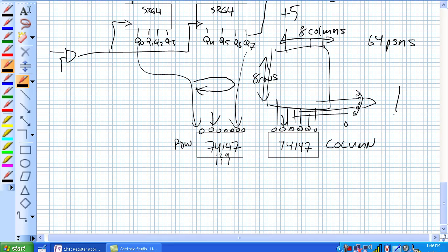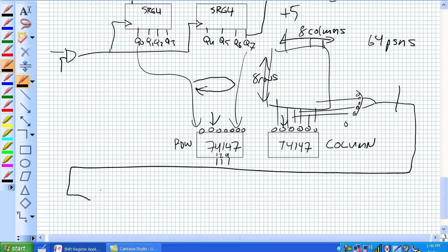So now, what happens there is, let's pause, let's hang out for a second via use of this one shot here. And all the one shot does is generate a pulse, and it inhibits that clock. Basically it's saying 1 the whole time, and because 1 ANDed with a moving clock signal is always going to be 1. So, okay, stop. We got something. Let's read what it is.